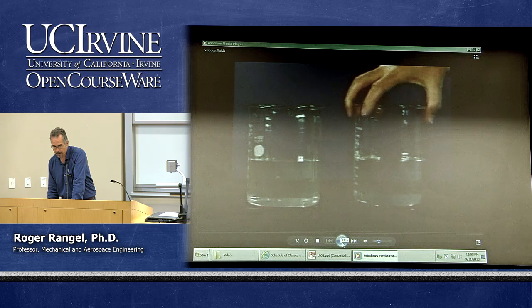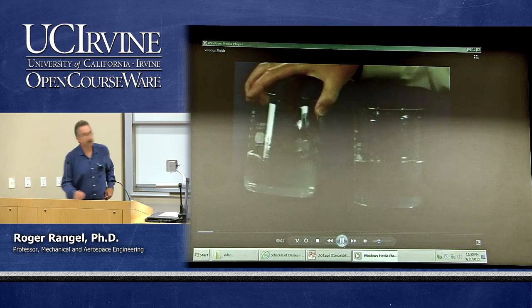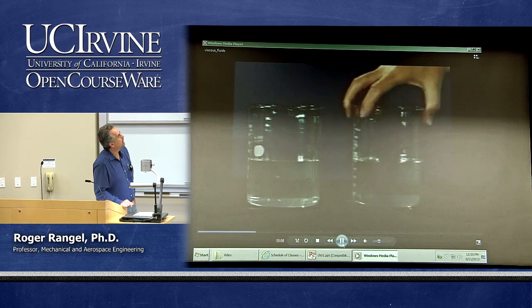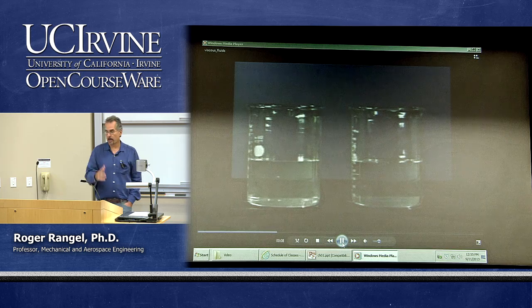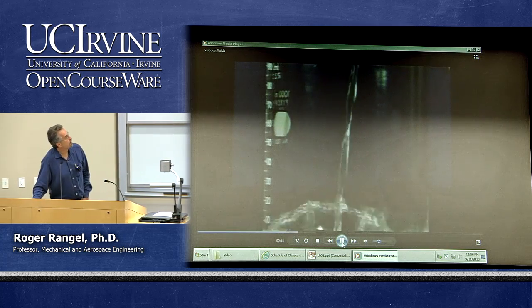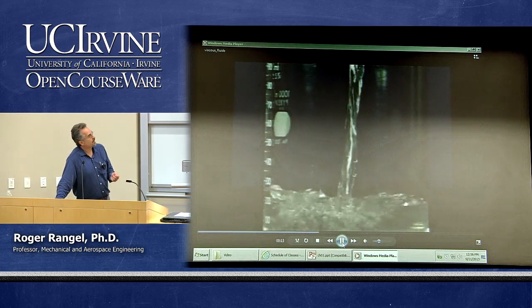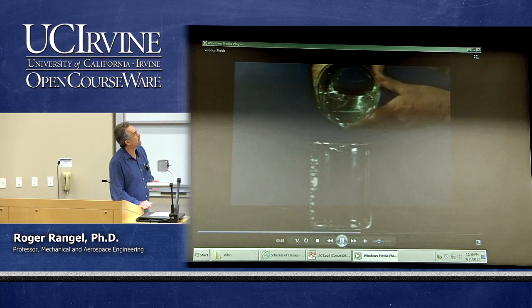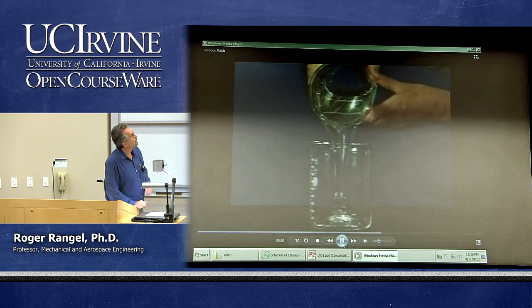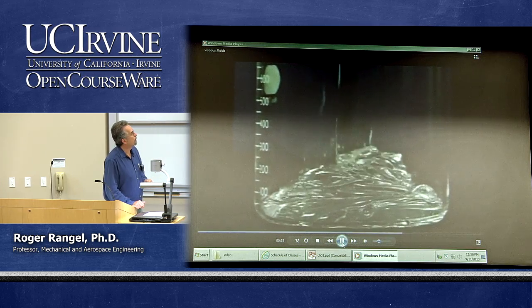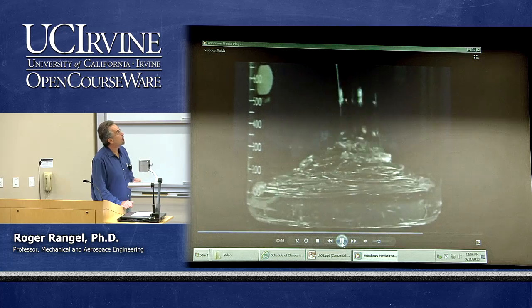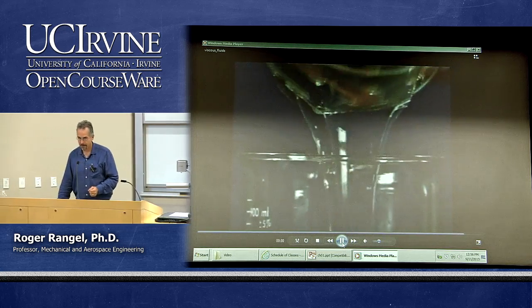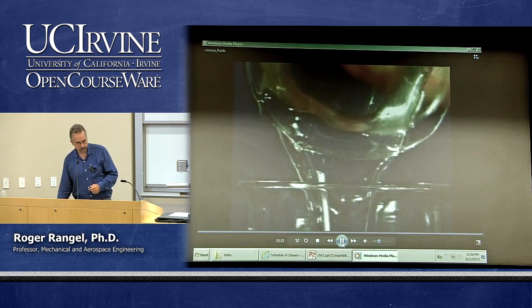One of them is water, the one that we will see first. So if you take water, you're all familiar with how water behaves. The other one is actually silicone, which has a much higher viscosity than the viscosity of water. Again, keep in mind they have the same density. So the density is not the issue. The density is about the same. What is making the second fluid, the silicone, flow in a much slower way is the fact that it has a much higher viscosity. So let's talk about viscosity.